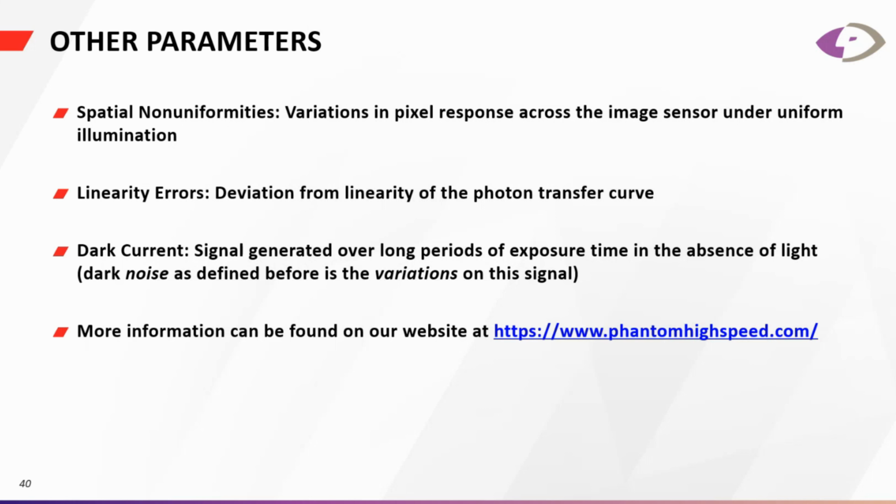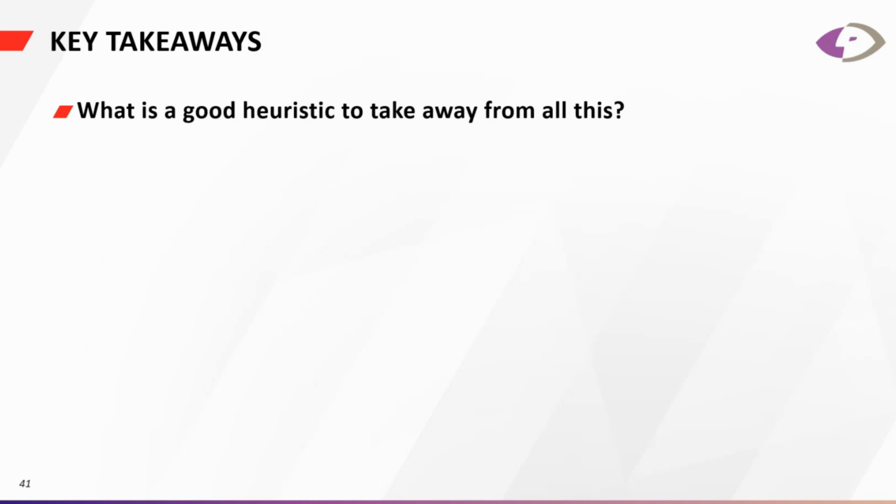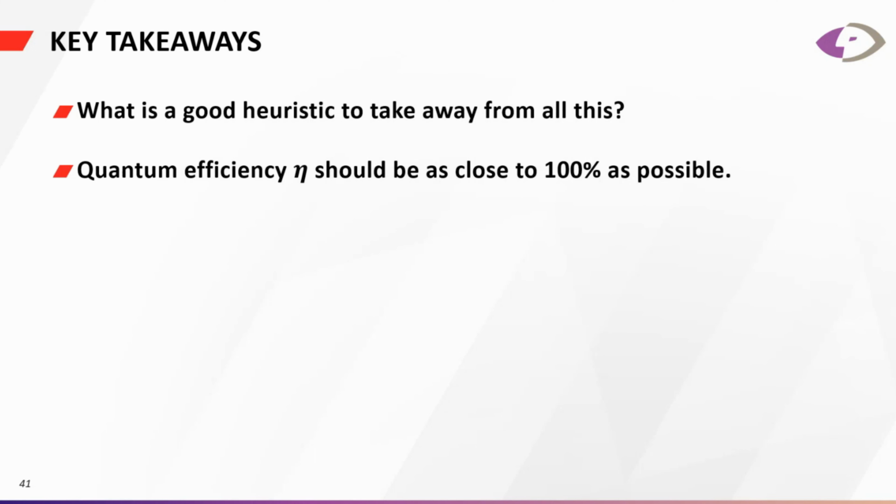Key takeaways. What's a good heuristic to take away from all this? What do you need to know in order to determine whether this camera is more sensitive or less sensitive than a comparable camera? First, the quantum efficiency should be as close to 100% as possible.